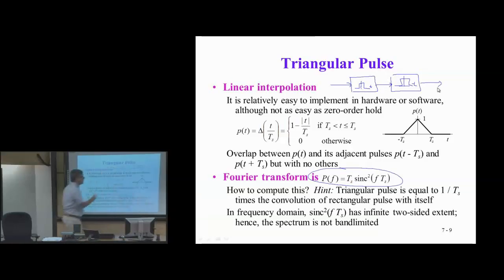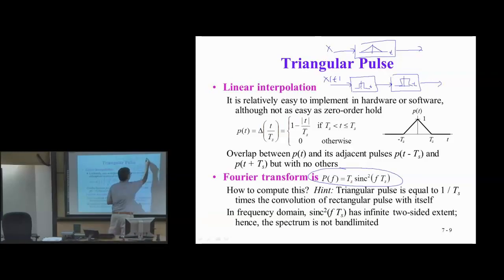Or, with two LTI systems in cascade, the impulse response is convolved, so I can write this as a composite filter. That's the wider triangle. These are equivalent. I'm in continuous time here.